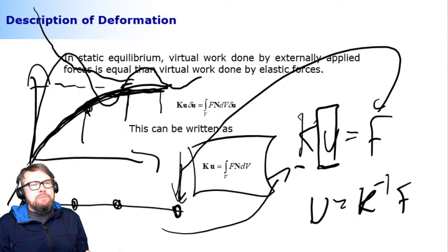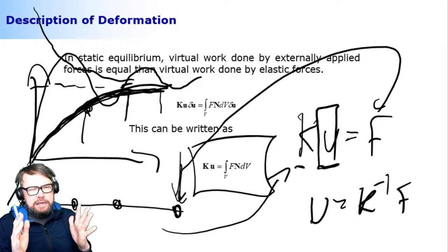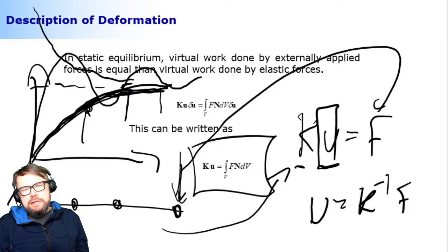And here is a very important lesson. It's really, really hard to know if you have an acceptable solution in your finite element method. The best way to do it is by making a denser mesh and seeing if that affects the results. And if it does, then you even need to go further. You need to do one step ahead. You need to check if this is still affected by a denser mesh.